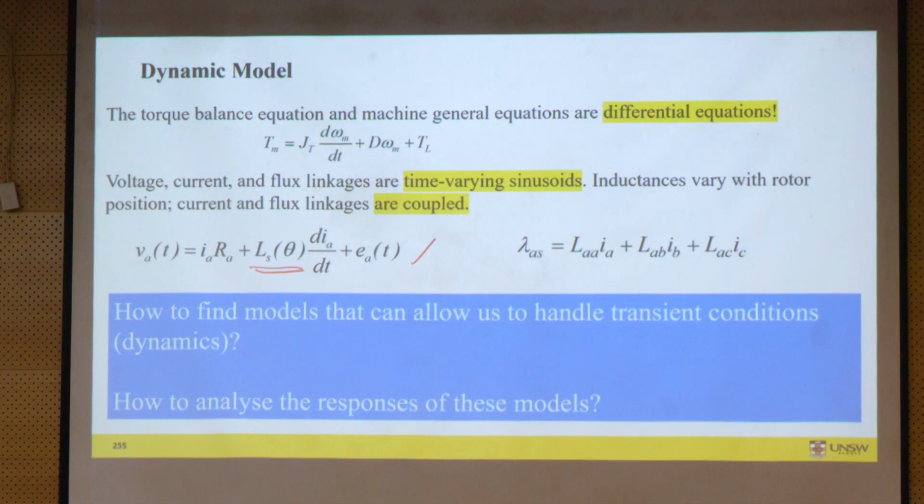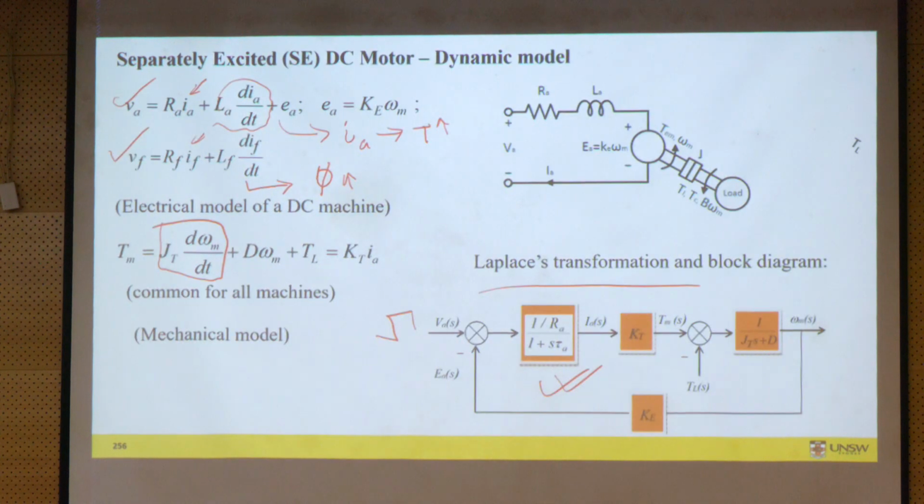The torque from the motor is actually a function of current and flux, and they are coupled to each other. This flux is the resultant stator flux, which includes the PM flux as well as the current flux. Flux linkage, I mean. So again they are coupled, and separation is not as easy as it was in the DC motor. So if we can get a torque equation in which we can see how the torque and flux are decoupled from each other, that will also be useful.